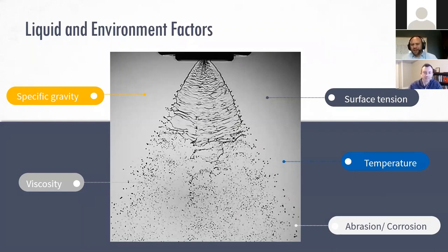It depends on the rheology, but Kyle, I'm sure it's very dependent on the type of material, what the material properties are, and then what type of atomization technology you are looking at. We're going to touch on some hydraulic sprays, using pressure-based atomization, but then you can have air atomizing sprays, which tend to make finer droplets. Someone else is bringing up electrostatics, ultrasonics, different technologies. So it's really dependent. Typically, at lower temperatures you're going to have a higher viscosity, and in that case, the spray droplets or the liquid material will tend to stay together as it leaves the nozzle, and so you end up with larger droplets.